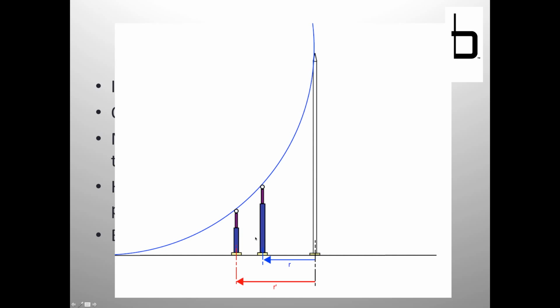And then we're given a strategy. As opposed to just randomly putting masts and wires out there and seeing what we get, we can have some idea of, if I put my equipment within R, then I know I'm good. This is also important because as you protect a substation, you're going to have several different equipment heights. Some equipment may be 20 feet, some other equipment may be 30 feet. So you really should do a protection calculation for different heights.